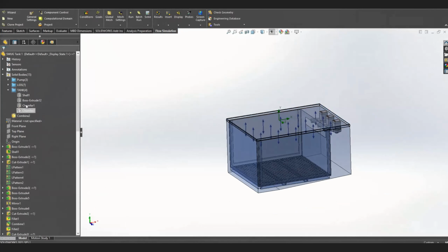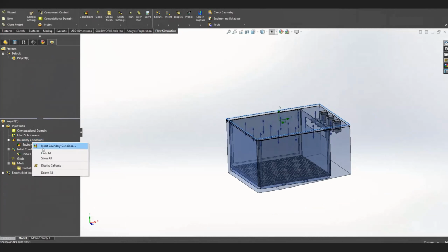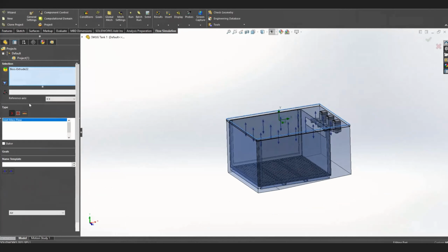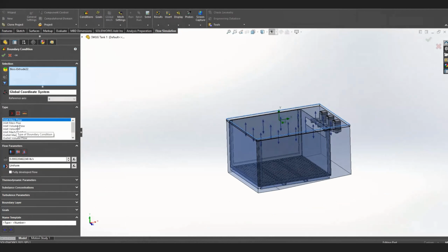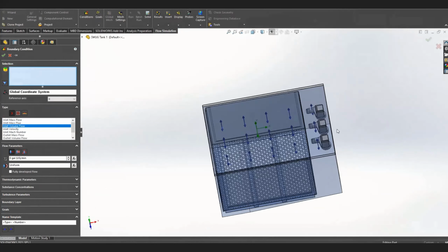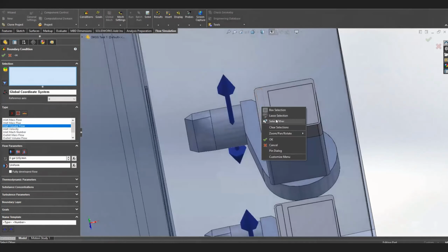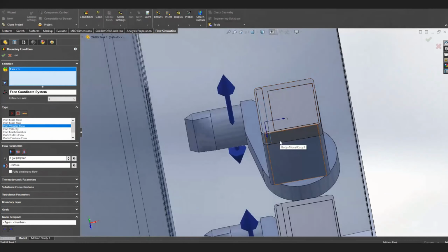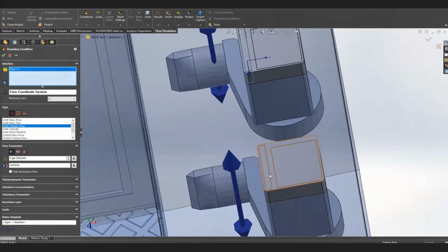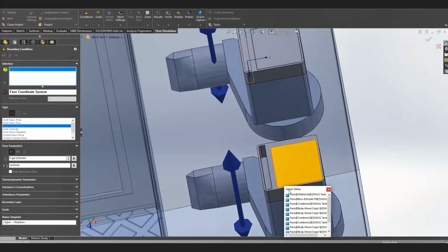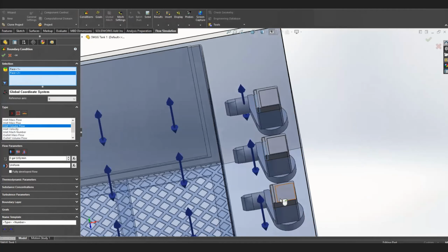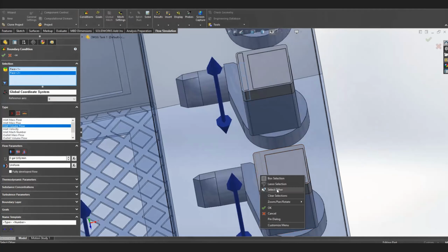And then I'm going to hide that so now I can access my other lids, my interfaces. And so I'm going to set an inlet flow on these pumps. Now, in reality, what these pumps are doing is recirculating the water in the tank. It's a little difficult to simulate perfectly, and I don't want to have to simulate a propeller moving the water around.